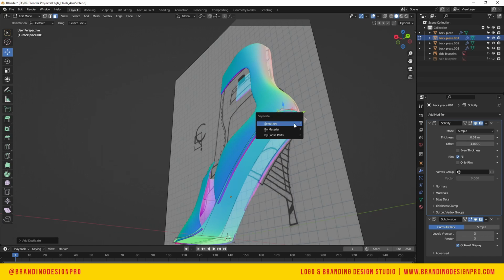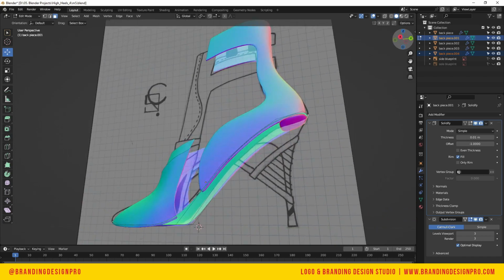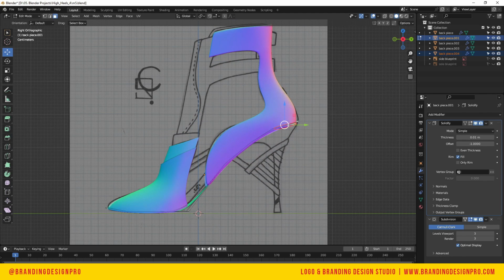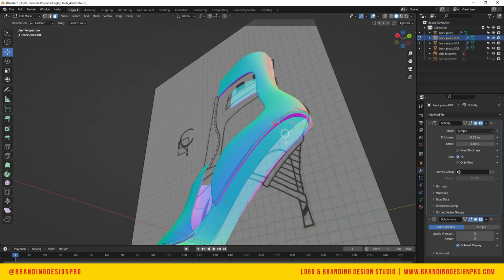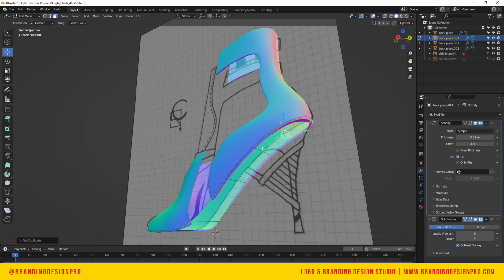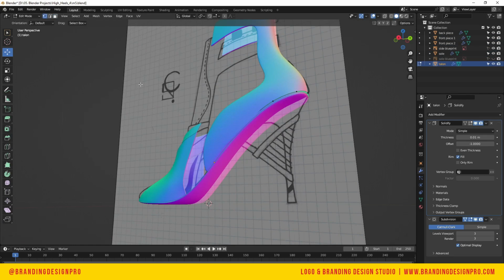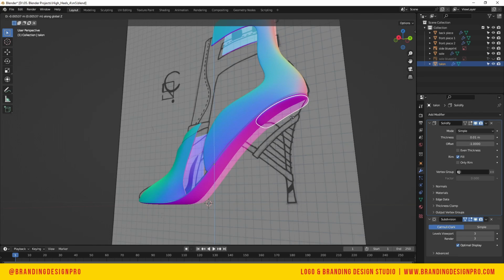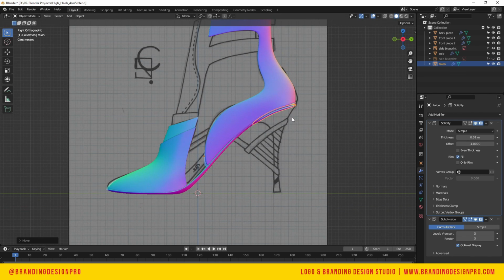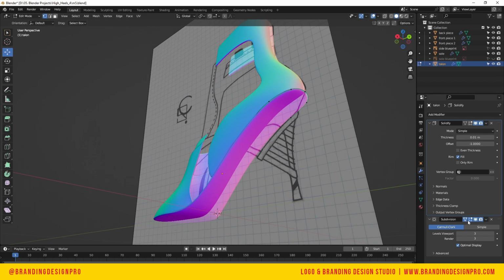Actually, I selected the 2. Let's go back, Control Z. Select the 4, and then turn on all of the vertices and geometry parameters and subdivision. Then Shift D and P to separate it. Once you've done that, you can turn those off. Actually, leave them on.